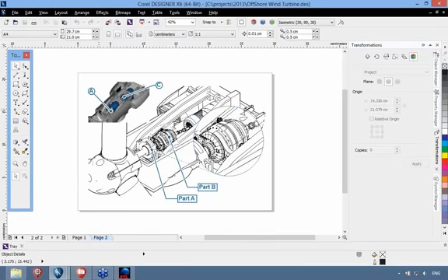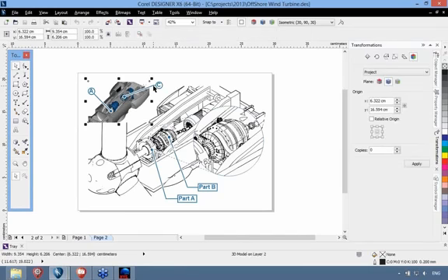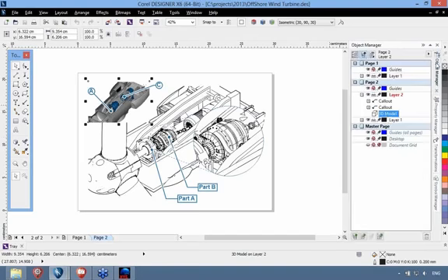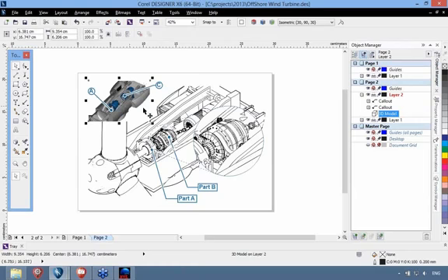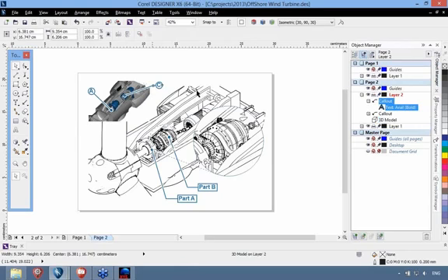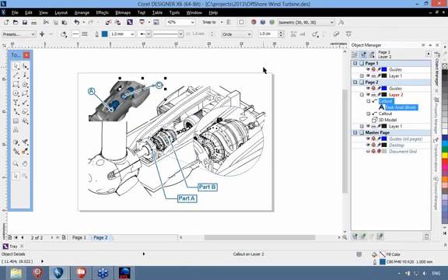Now, one new thing, you can make your callouts now stick to a specific point or object in the drawing. So I have my imported 3D model here again, and I can move that, and what you see here, only the leader line of that callout is moving, and the callout text is keeping its position. You can change that to make the whole callout follow the source objects, the origins. So that's something that you can specify in here to move the whole callout, or to only move the leader line and the starting point of the leader line.